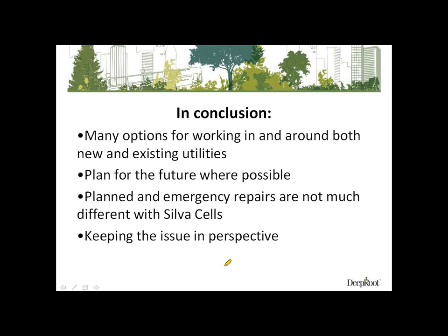We plan on having a 1 to 2 inch void eventually as the system moves along for air exchange. So the soil not being compacted, along with that void underneath the decks, gives you some room for the frost heave, expansion and contraction of the soil during those different warm-cold cycles.